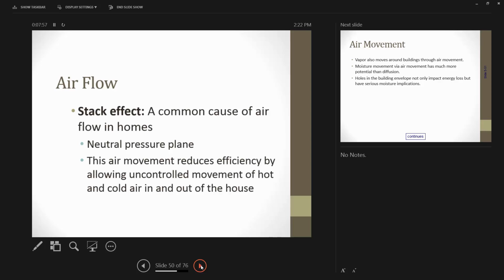If you've got a multi-level house that's very, very leaky, you've got a heating system, it heats the air, that air warms, and as that air warms, it rises, it leaks from everywhere. And we'll go through this when we look at our thermal bypass checklist, but it leaks out of electrical outlets, it leaks out of lighting fixtures, it leaks just through connections of interior walls to the trusses, it leaks around the windows and doors, it leaks just about everywhere it possibly can. And so the warm air rises and leaks, and it's got to be replaced with other air. So it's just constantly moving, cooling down the house.